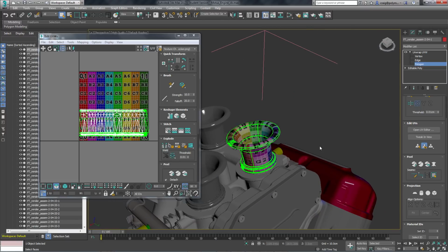So that's a quick overview of how we can work with UVs here in 3ds Max. Let's take a look at how UVs work with Unreal, and there are a couple of things to consider. The basics: what are UVs needed for when we come into Unreal Engine? Well, we looked at the idea of texture maps, right? Diffuse maps or color maps, maybe things like bump or normal maps, or any kind of displacement that we might want. That's the visual basis of image-based textures. But we have this other world of light maps, and this is the second channel that is required.